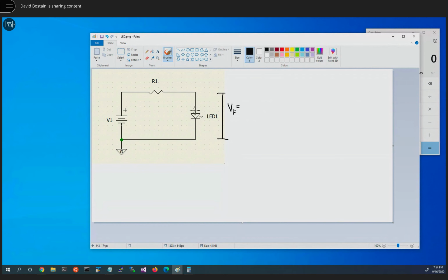Okay, we know this is not a regular diode, and remember I drew you a different picture for an LED. I said it doesn't start happening until V forward, which is at 2.1 volts. So you make the assumption when you're working with LEDs, instead of 0.7, you make 2.1 volts be that forward voltage.